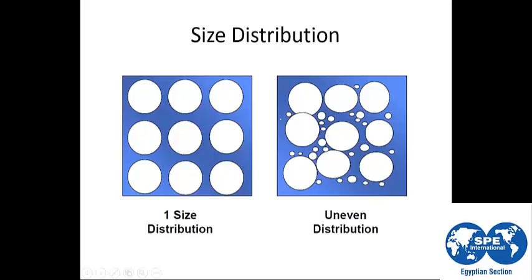ceramic proppant. But for natural sand, if you are going to use it, you will spend a lot of money on sieving the sand to get the required particle size distribution. And even if you get the correct particle distribution, the sphericity and the roundness of the sand particles for sure will not be comparable to the ceramic proppant.